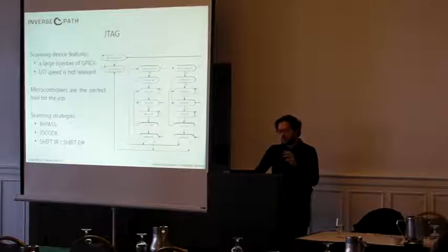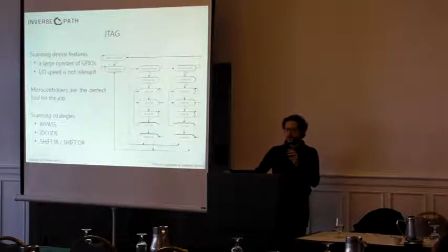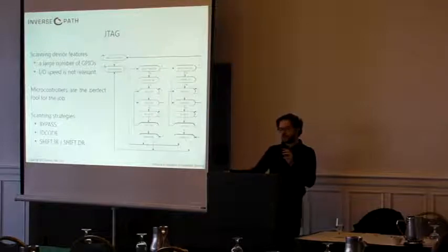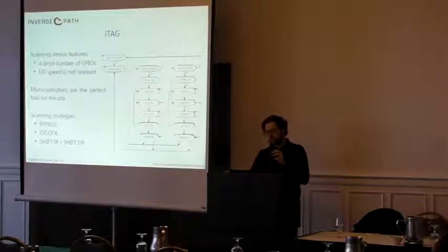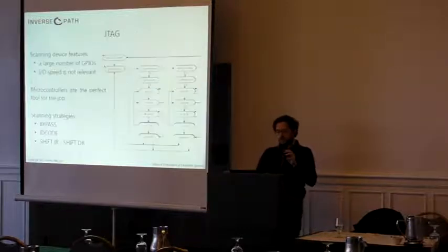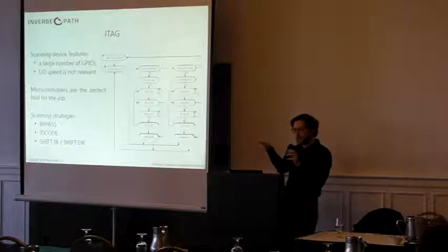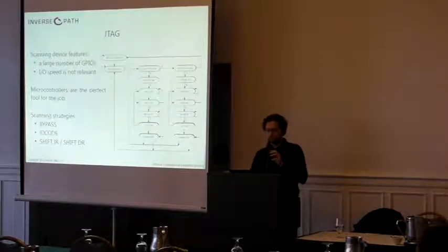So there are some interesting challenges when doing this, and there are a couple of projects that you can find online that help you in finding and scanning the JTAG pins when you think you identified them. They're not as complete and as efficient as we would like them to be, but they're a very, very good starting point. And you can easily modify them to obtain what you want and to implement your custom initialization sequence in them. And usually microcontrollers are a great tool for playing with this kind of access and implementing your own